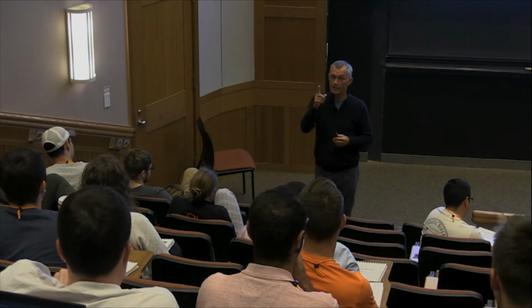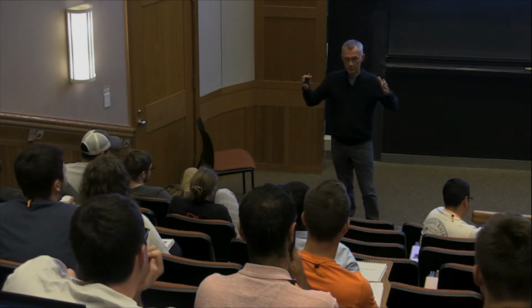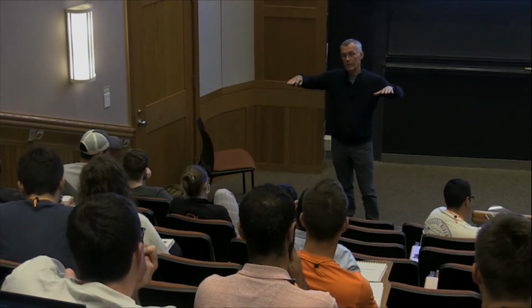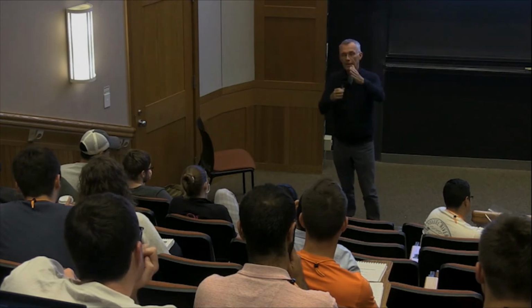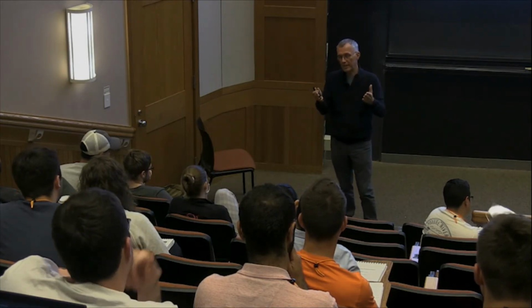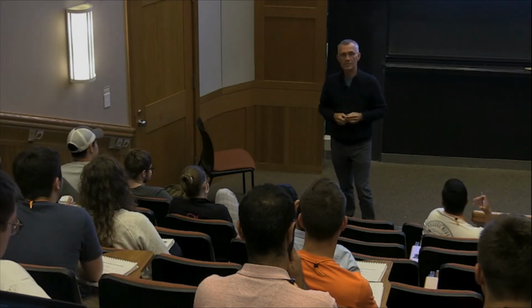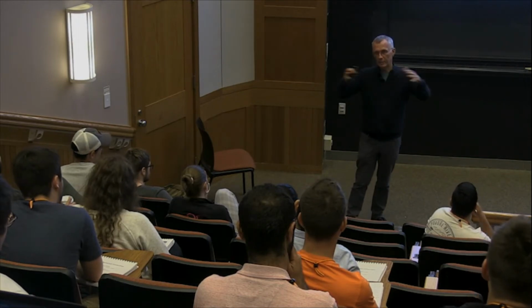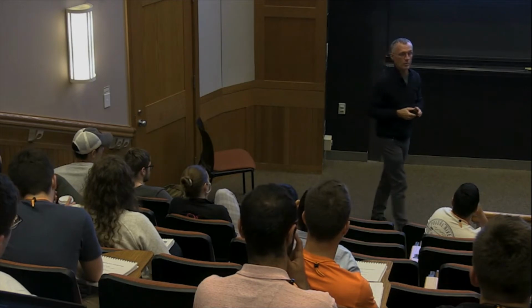Yeah, but that's what I said. Of course, the total energy is the same. The difference is that when you burn slowly, it's the same everywhere, it's homogeneous. And when you have a shock, it's less here and more at the flame. So again, on average, it's the same. But if you are sitting at the point of maximum pressure, you're in trouble. If you come back after a long time, everything will be the same. But it's really during the transient phase that the shock will be important.